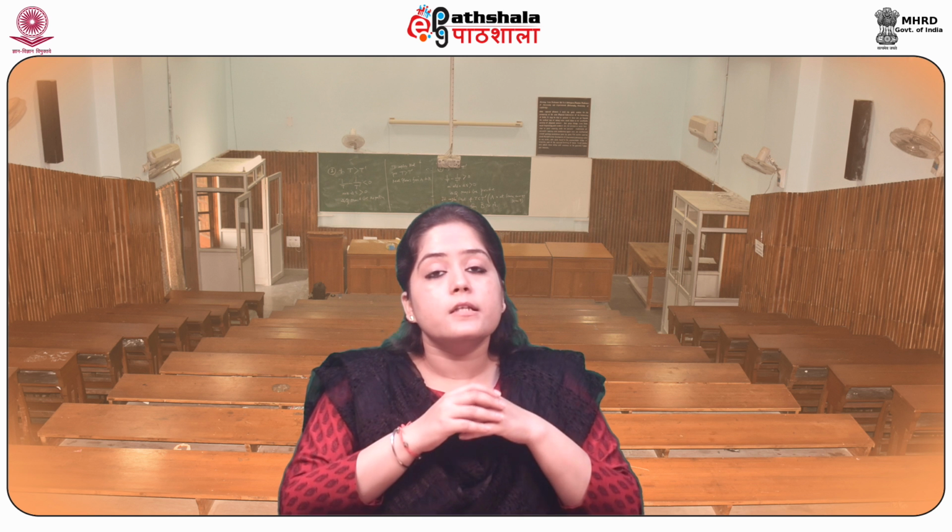Thirdly, various types of noises, that is inherent fluctuations, thermal or Johnson noise, shot noise, 1/f noise, quantization noise, high frequency or transit time noise, and generation recombination noise, were all discussed in this module. Next, we discussed the contribution of the equivalent noise resistance. Then another important parameter, that is noise factor, was discussed,